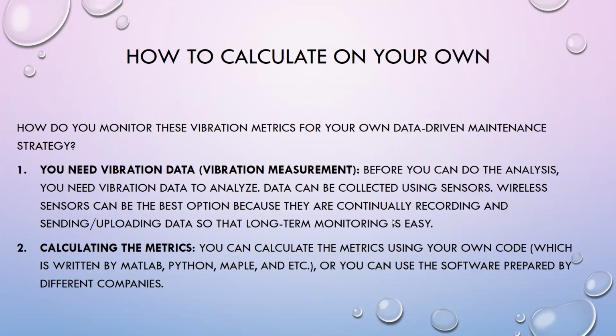Okay, to calculate these results, as I told you, the first step you need to extract the data. For this purpose, you can use different types of sensors or different types of equipment. But the equipment that I use and I suggest you to use is the accelerometers, the portable accelerometers and the wireless sensors.